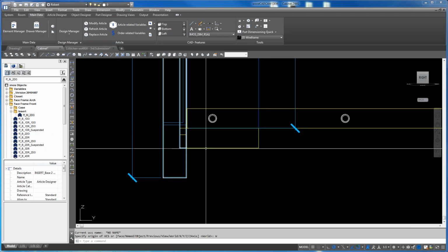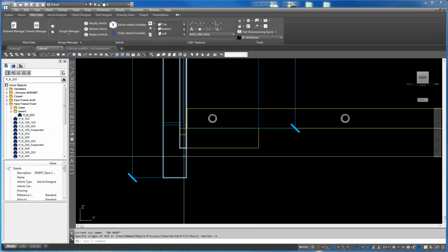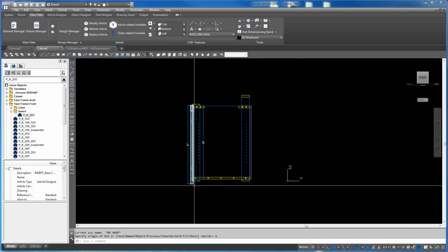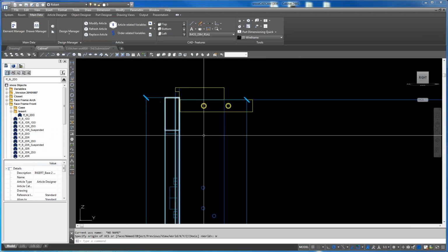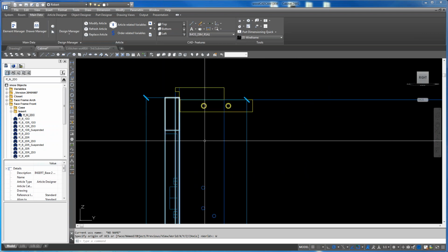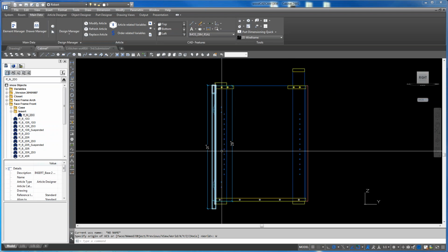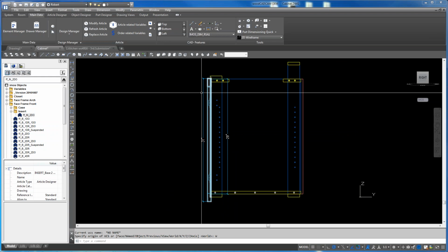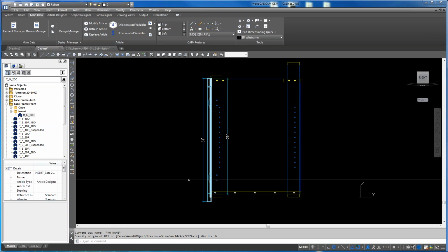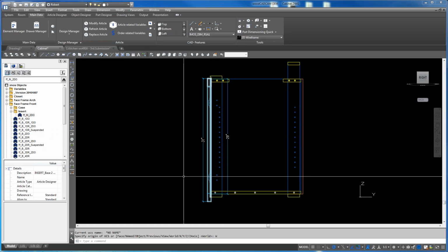So our filler will always be behind the face frame. You need to adjust the top of that, right? Yes. And still, the 31 inch that I have, the face frame, should be 30 and a half.